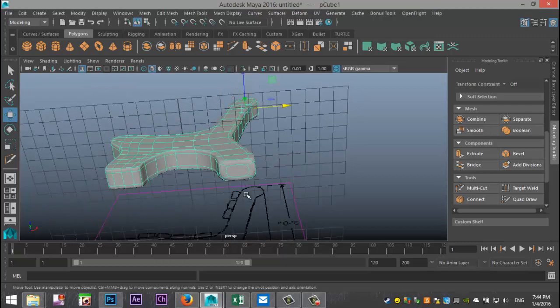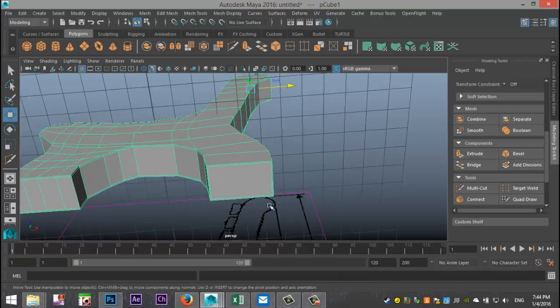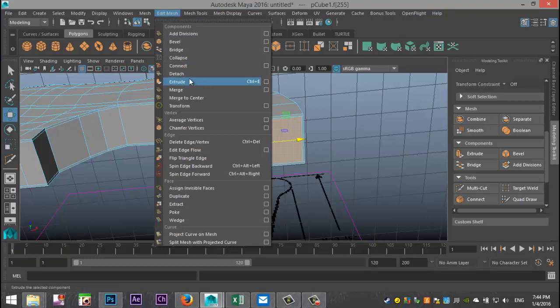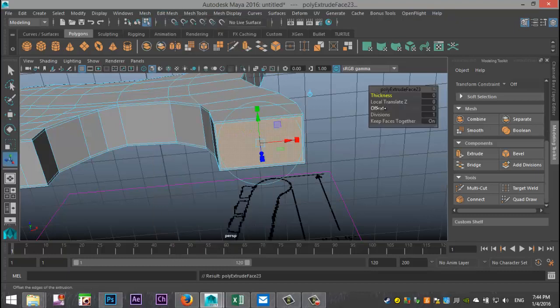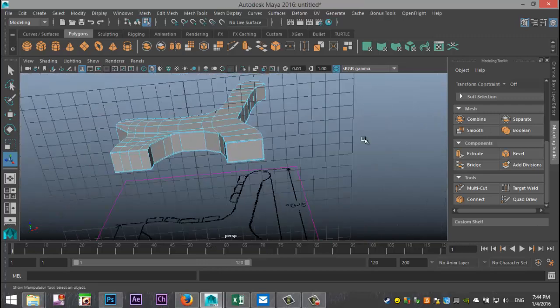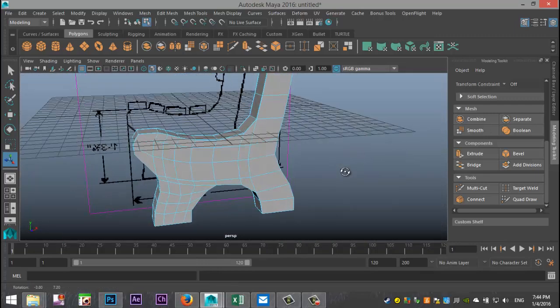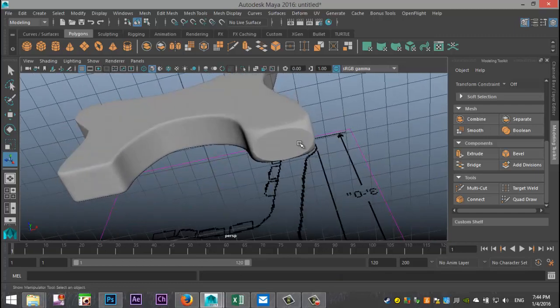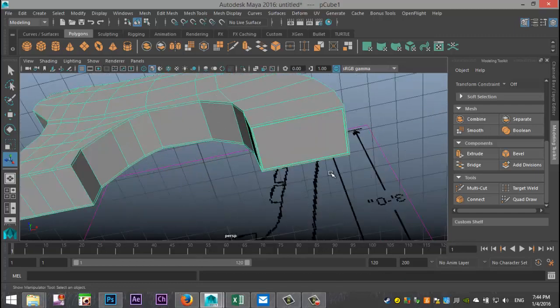Okay, not quite so much here. So another little trick we can do is right click at a face, select that face, edit mesh and extrude. We're going to tweak the offset just a little bit. We'll do 0.01, okay, which creates an additional face on that surface, which will make it look better. So right click object mode, 3 to hit that again. Still not there yet.